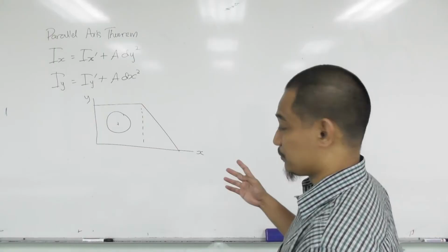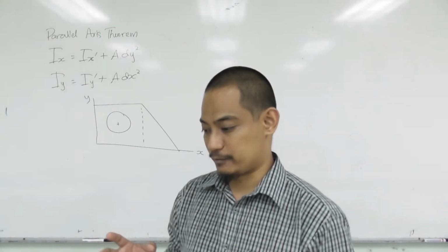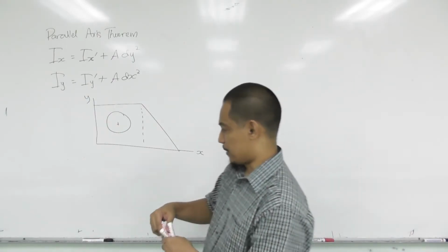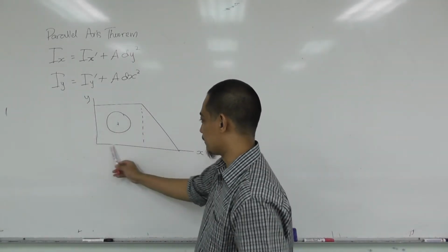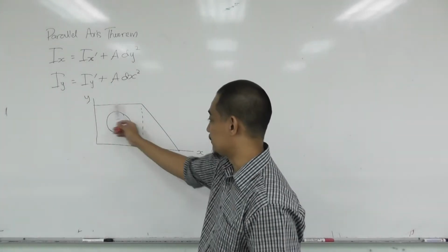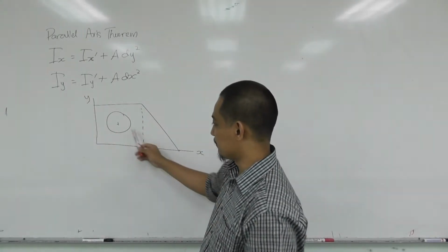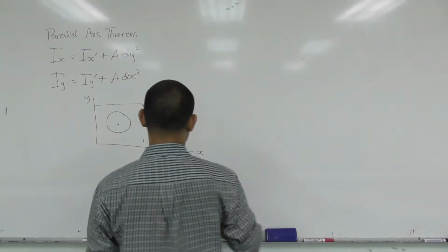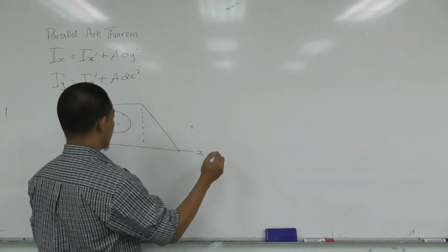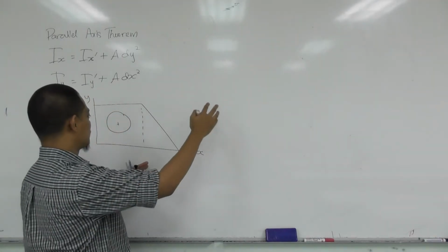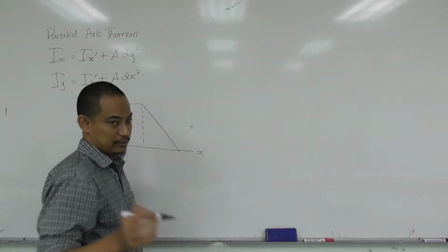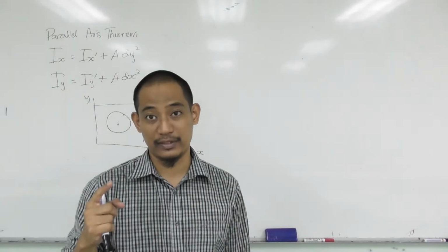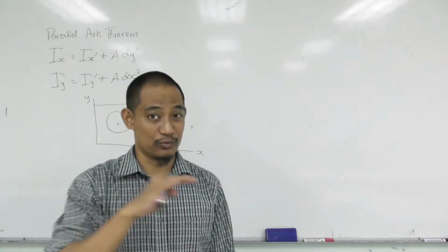Right. So basically here you have several ways of dividing the shape, the area, right? So let's do this rectangle here, plus this triangle, minus this circle, right? So in that case, this equals, if I redraw it, hopefully a bit smaller. And make sure you understand the question. The question asks, what is the moment of inertia about the x-axis? So our base is always the x-axis, right?